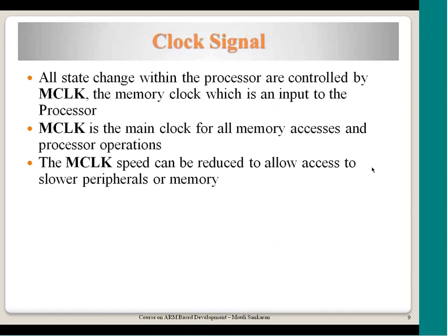You may wonder why this kind of flexibility is given in ARM. When the ARM IP is made, it could be integrated with any kind of system. It could be with a fast clock, or it could be integrated with memory and other systems which are very slow because power requirements are less, for a low end application. Then the processor should be configurable to run at any speed.